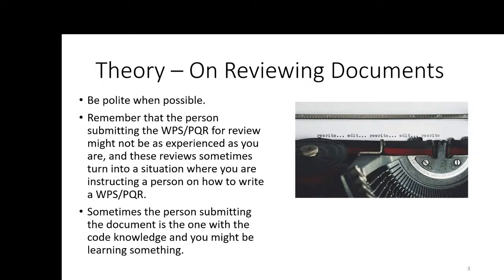Remember, the person submitting the WPS and PQR for review might not be as experienced as you are. These reviews sometimes turn into a situation where you're instructing a person on how to write a WPS or a PQR. A lot of times I've had to do that, because the person writing it wasn't very knowledgeable on welding or welding codes. So I would use this as a tool to help get my vendors up to speed, and you can pass on some good information using this form.